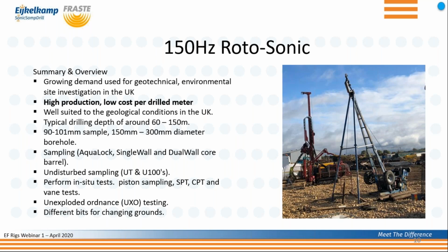We're seeing quite a lot of contracts specifying sonic in the London area at the moment. Of course, it all depends on the size of the rig, but your typical drilling depth is usually between 60 to 150 meters. 90 to 101 millimeters are the standard sample diameters, which are often used for geotechnical sampling. And generally, the borehole diameter would sit around 200 millimeters.